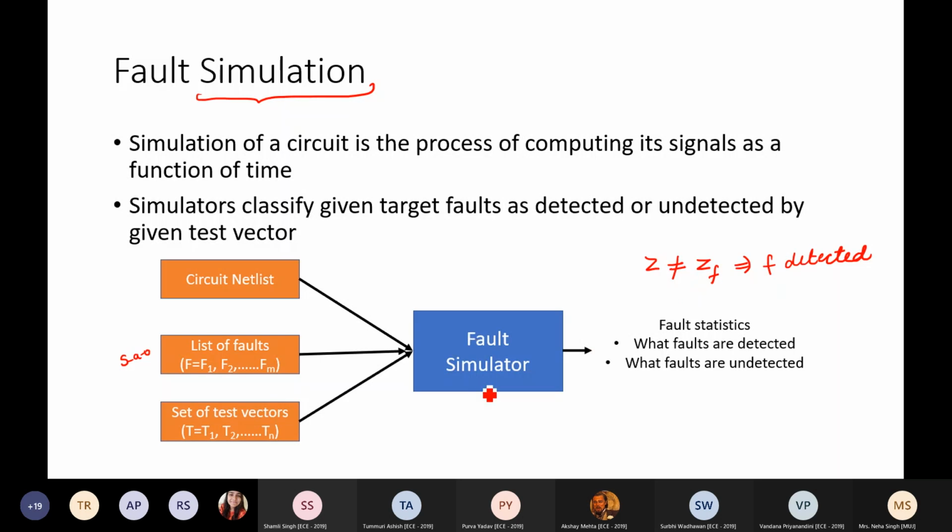So basically what we are doing in a fault simulator is we are reading the circuit, giving it the test vector which is used for a fault free circuit first. कोई भी fault हम assume नहीं कर रहे हैं, neither of these faults exist, and we give the test vector and we generate the output to know what is the actual value of Z. Then we introduce one fault at a time because हमने क्या पढ़ा है, हमने पढ़ा है single stuck at fault consider करना is very safe.